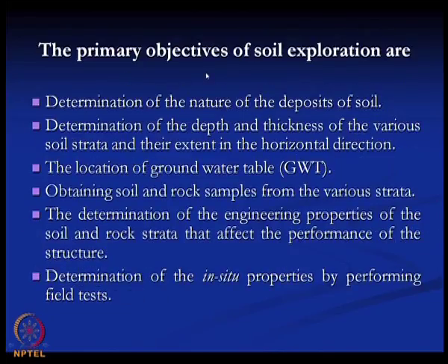Now, the primary objectives of the soil exploration are the determination of the nature of the soil deposit, and the determination of the depth and thickness of various soil strata and their extent in horizontal direction. What is the depth and what is the thickness of the various soil strata is very important for any foundation design.